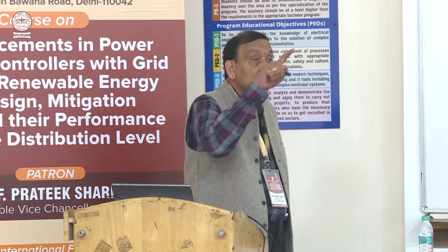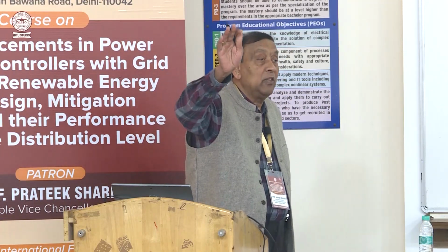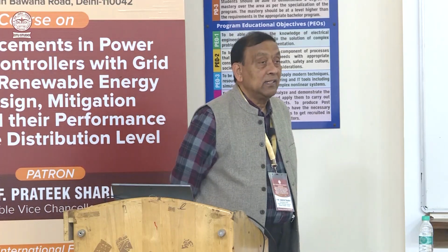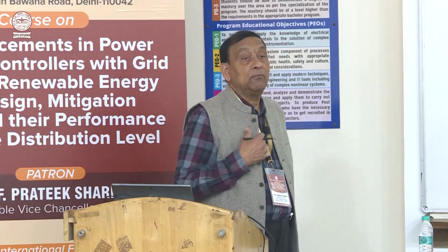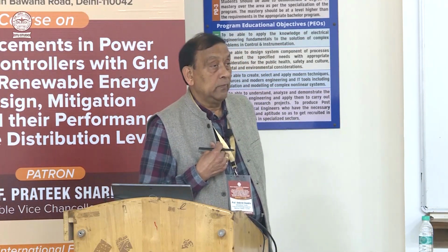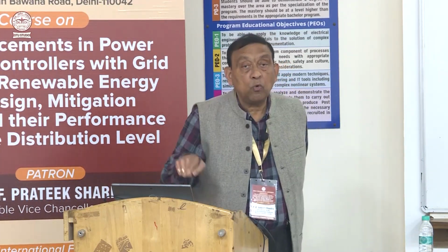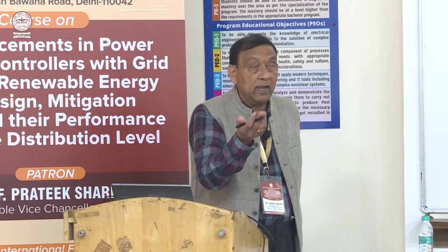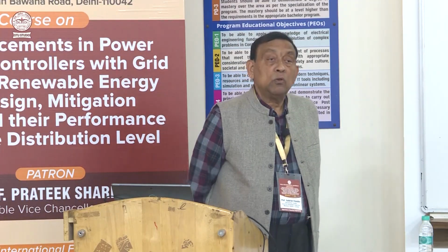So if you increase the number of poles, then the diameter of the rotor will increase. So this is what is happening. Enercon has developed annular generator type PMSGs. They have the large diameter to accommodate even 100 poles or more than 100 poles. That depends on the capacity of the machine. So the diameter, so there is the advantage.